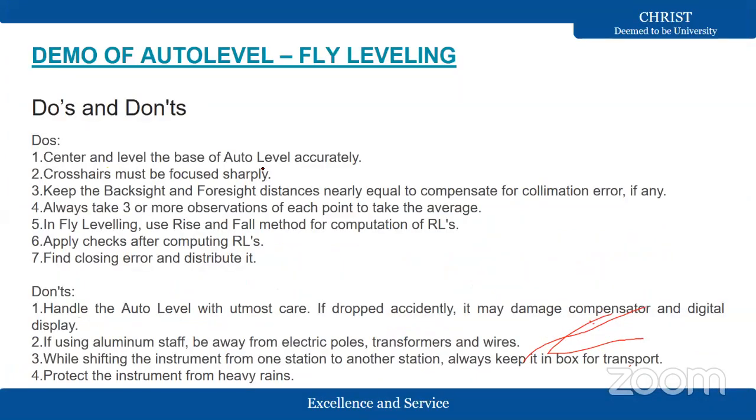Okay, next, I am going to give a demo for auto level by using fly leveling. These are the precautions written over there, do's and don'ts. First, whenever you lift the instrument, you have to transfer the instrument with the casing. You cannot take the instrument naked.